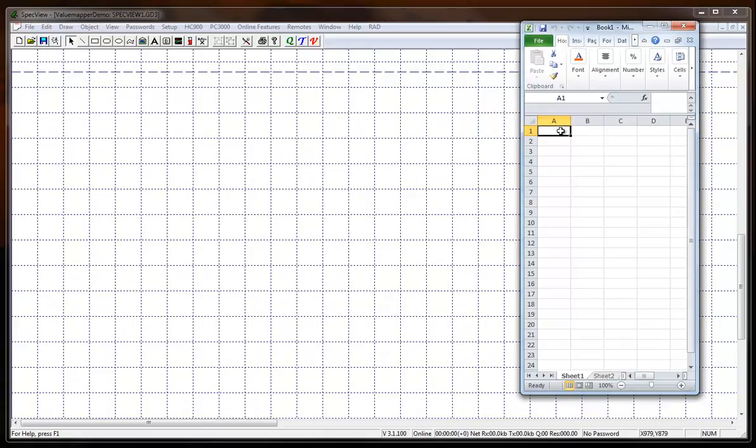So you might send your thermocouple away to a calibration service and get back a result that says at 0 degrees the thermocouple is bang on, at 100 degrees it reads 1 degree too high or too low, or whichever it is, 200 degrees it's -1, and at 500 degrees it's 6 degrees above, let's say. Simple little table. The value mapper ActiveX control interpolates values between them.